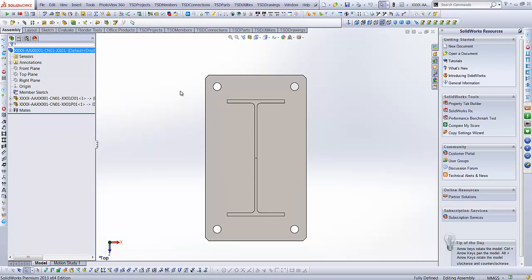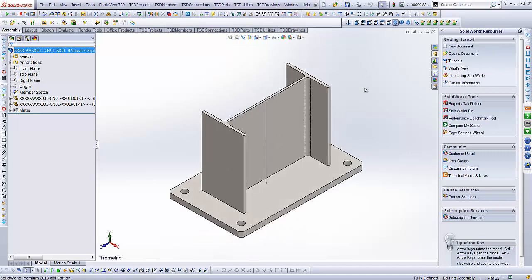If you have too many configs in a model or too many configs in an assembly, you can end up blowing it right out, and your project ends up being massive. I mean massive. I've seen them get really big. Every time you create a new config, it creates more data in the file. It has to handle it, and thus the size of the file grows. I've seen 100 meg connections being created, so just be wary that these files do grow.